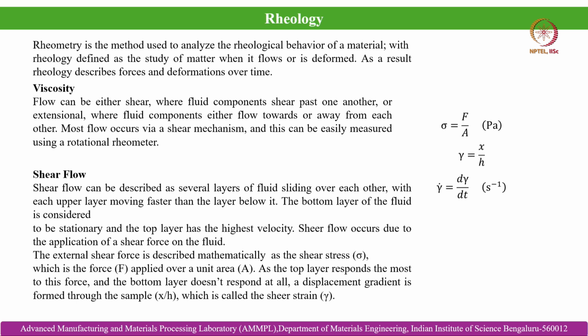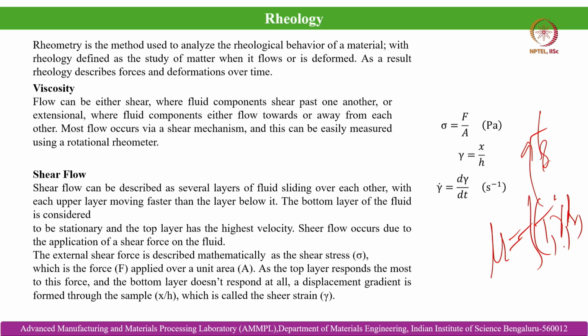Viscosity is a function of temperature, which also governs the solid content Fs within the solidifying melt. It is also a function of shear rate, microstructure, history effect, and so on. But primarily viscosity can be defined as a function of temperature or solid fraction and shear rate.